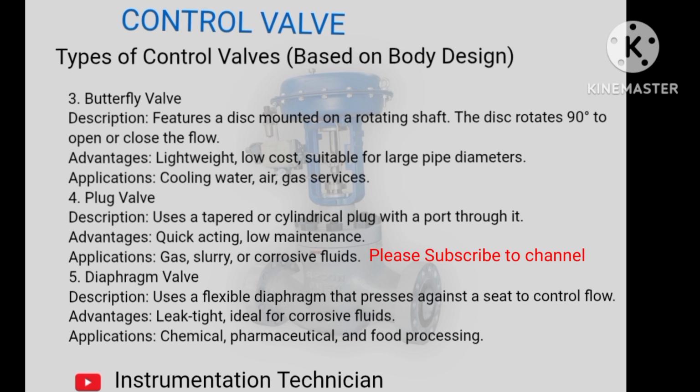3. Butterfly valve. Description: features a disc mounted on a rotating shaft. The disc rotates 90 degrees to open or close the flow. Advantages: lightweight, low cost, suitable for large pipe diameters. Applications: cooling water, air, gas services.